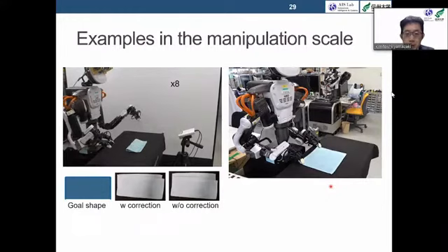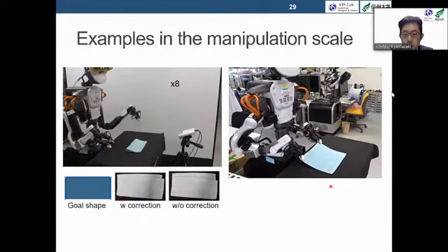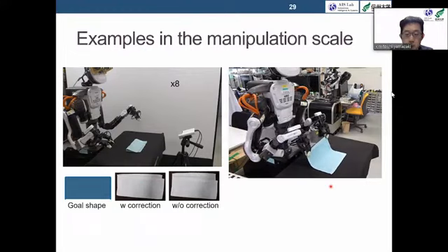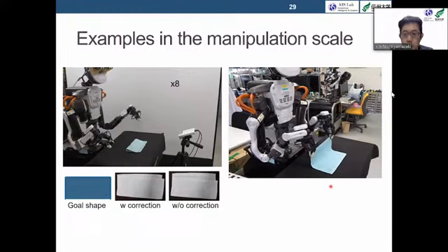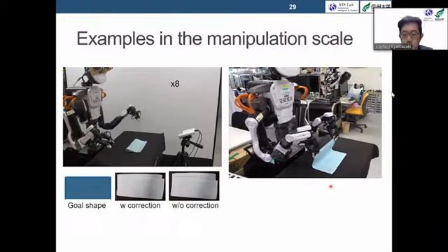By the way, the robot's motion is not smooth in this movie. This is because a new trajectory cannot be generated until the shape prediction result is known. So a wait time is required immediately after the estimation. Since this does not look good, we built a control loop that takes the delay into account. As shown in the right movie, the result is smoother and quicker motion.